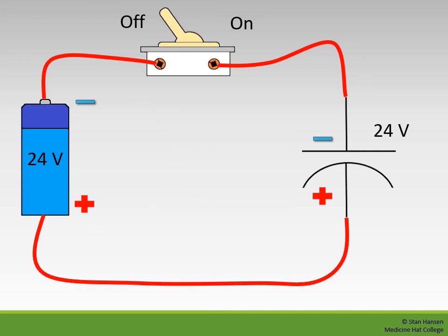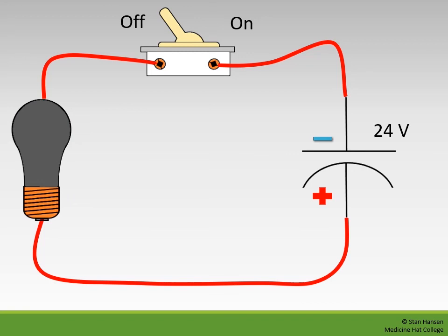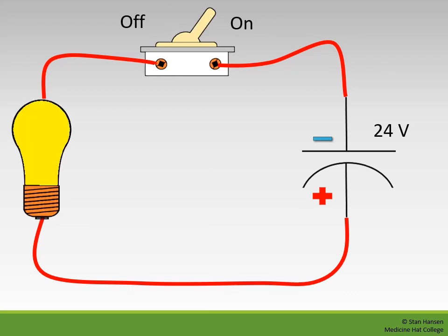After the capacitor is charged and we open up the switch again, we find that the charge stays inside the capacitor. Without a discharge path, a perfect capacitor could remain charged indefinitely. When we put a load into a charged capacitive circuit, the capacitor now will supply energy to the load. The electrons will leave the negative side of the capacitor, travel through the load, and go to the positive side in order to balance out the charge. When the switch is closed, the capacitor will discharge.